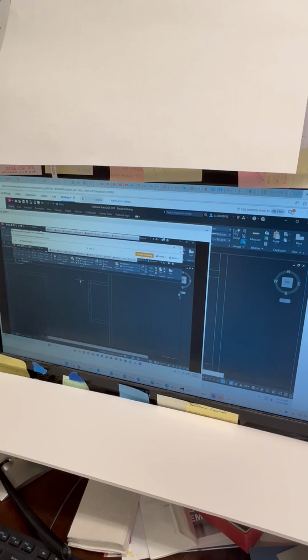But if something like this happens, one way you could approach this is you could delete these elements here and use your extend command and extend those over there. But look what you have to do. You have to keep going and you have to keep going until you get there. All right, so that restores that wall there. But I've got something I want to show everybody else that we didn't actually show yesterday. Let me undo.